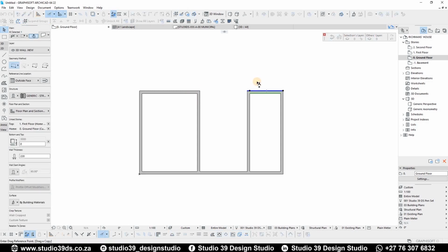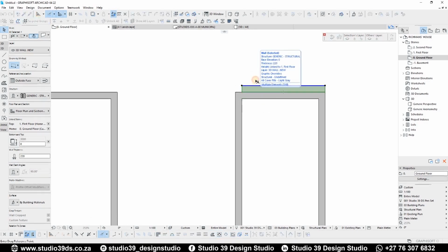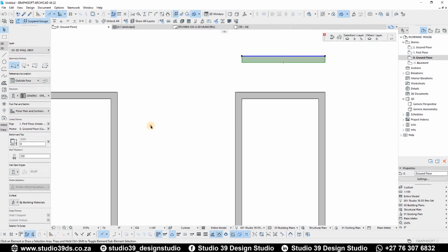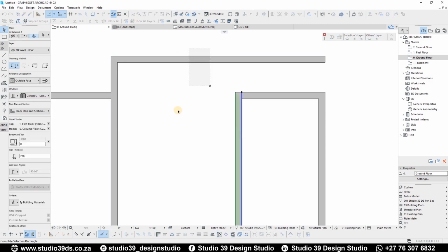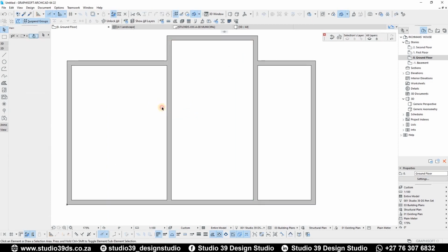The only reason I'm extending this way is that I'm going to drag a copy also right here, Control Shift D. See my other videos to understand why I'm using the shortcuts. Then I want maybe a 1 meter extension over there, and then select both of these and intersect, which I can just press I for, and then do the same thing here, intersect, and that's basically my basic form right here.